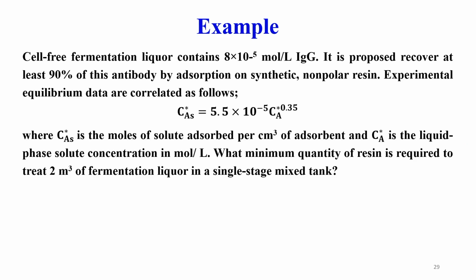Now, we will have a quick example here. Cell-free fermentation liquor contains 8 × 10^-5 mole per liter of IgG, and it is proposed to recover at least 90% of this antibody by adsorption on a synthetic nonpolar resin.